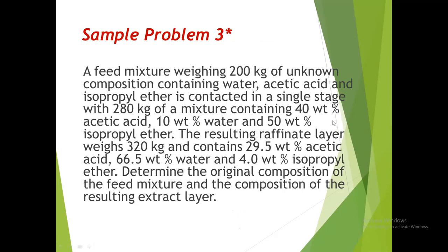A feed mixture weighing 200 kilograms of a known composition containing water, acetic acid, and isopropyl ether is contacted in a single stage with 280 kilograms of a mixture containing 40 weight percent acetic acid, 10 weight percent water, and 50 weight percent isopropyl ether. Now take note that in this case, your solvent, the 280 kilogram mixture, is not pure isopropyl ether. It also has the 3 components present in the feed.